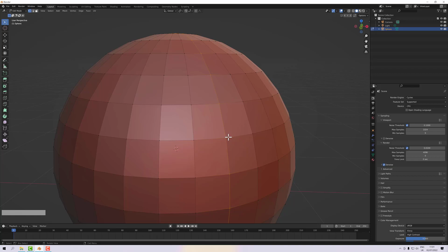But if I select just to the right of a vertex, you see it's now going horizontally. And if I select below the vertex, it's going vertically. So just be aware that you don't have to be exactly on something to actually select it. Basically, Blender will pick the nearest item for you.